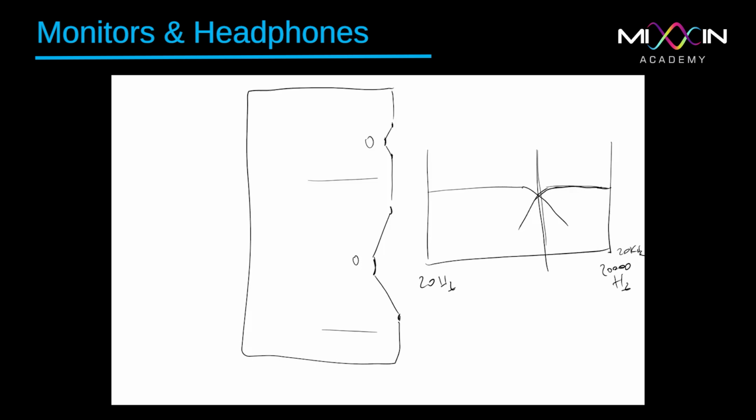But the manufacturer tries to keep this crossover point so fine that in the end we get a flat response. Of course, there is a question of phase too. So these crossover frequencies need to be in phase so that we don't have any distortion of sound. And I mean distortion in the sense of phase cancellation. But this is all done in the factory.